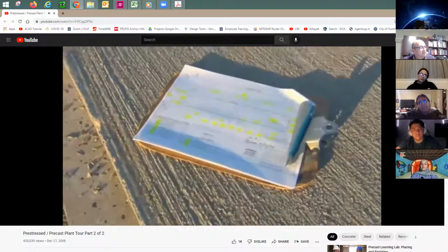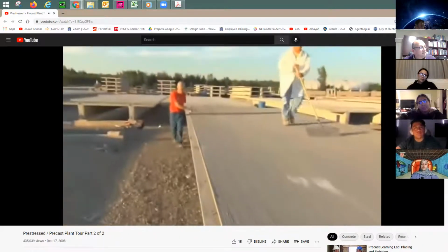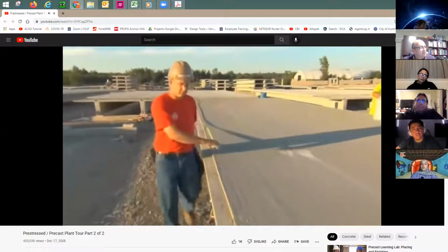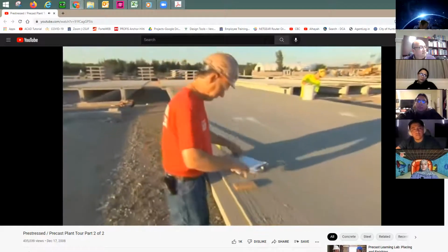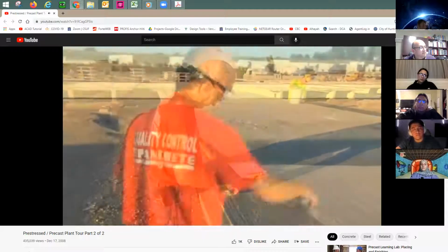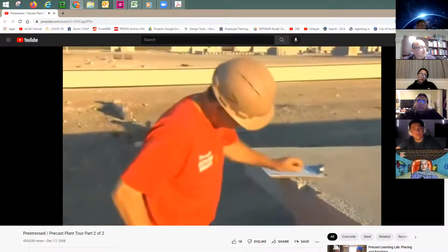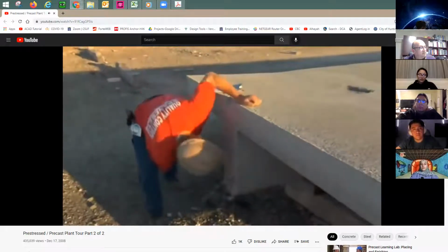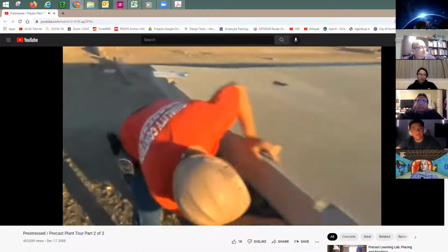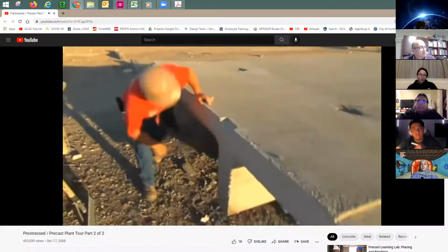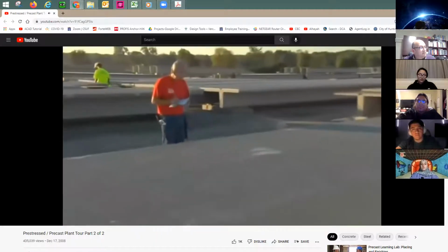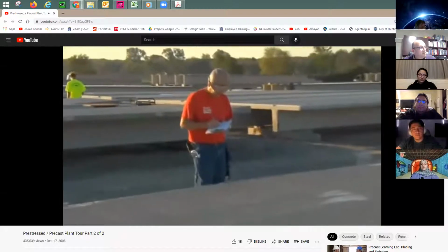When I first get back there, I go and check the length of the piece, verify that it's within a tolerance of probably a quarter inch or so. Check the width, we check the dimensions, we check the electrical blockouts. I do a visual for any type of discoloration in the stems underneath the piece, any type of surface cracks, bug holes, just do a complete visual. Any defects are noted so that repairs can be done before shipping the tee.